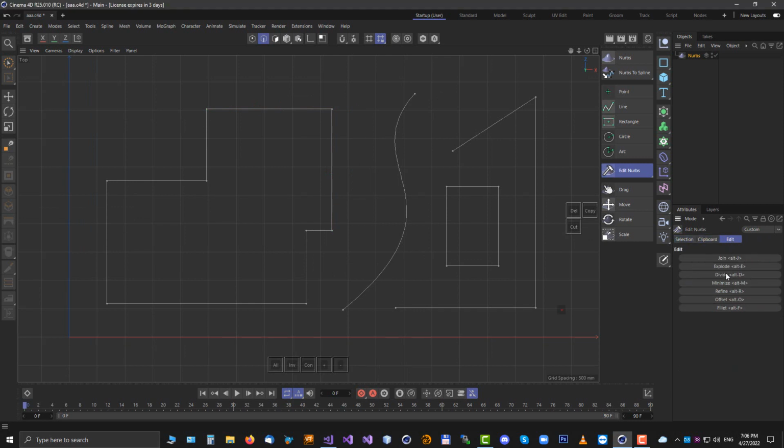Now let me show you all these new edit tools. First, the divide tool. With the divide tool, you can very simply divide selected geometry. So if you select edges, these line segments, then each line segment is divided. The divide tool has two basic modes, count and distance.